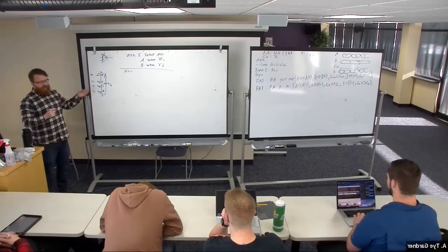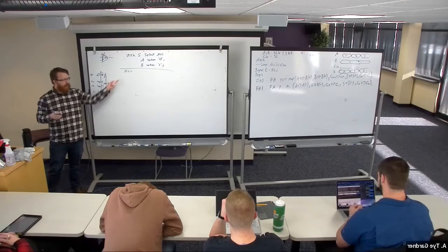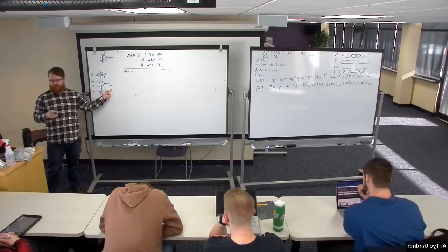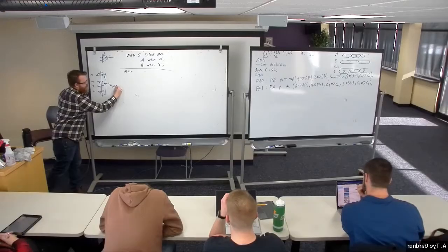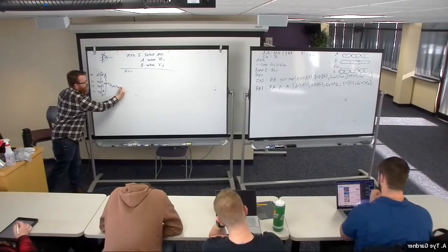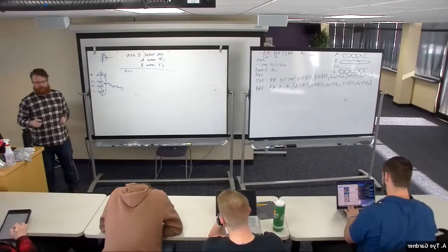Well, let's say we want to build this. But that means when I've declared the signal M, I needed to make it a 3 down to 0 vector, right? And this is M 3 down to 0. Now it's a 4-bit vector, matches my picture.